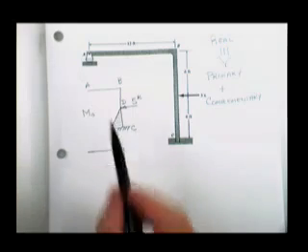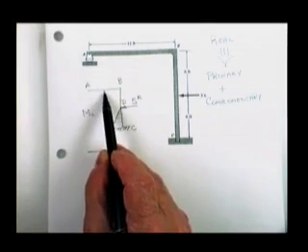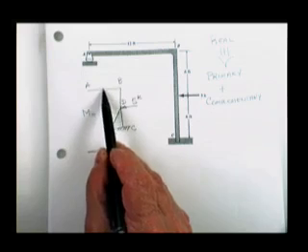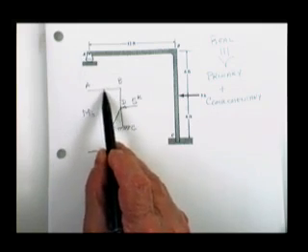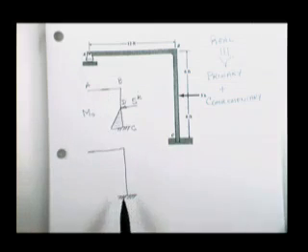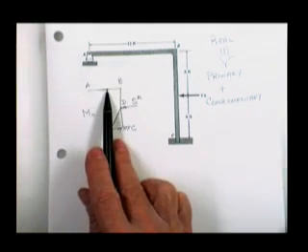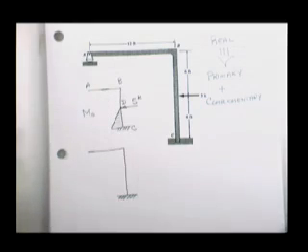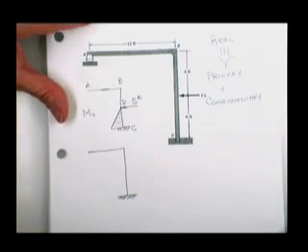Harrison, how much bending would you have right here? Harrison here today? Okay, considering the situation. How much bending would you have right in this piece right here? Down in here, I'm going to show you the whole thing all bent final. But how much bending would you have right in here? That is absolutely correct. It's a hard answer for a student to give because you think you're bound to have something, and when you don't think there's anything, the prof's picking on you or something. But no, there's nothing there. Because there's no moment there, there's no bending.